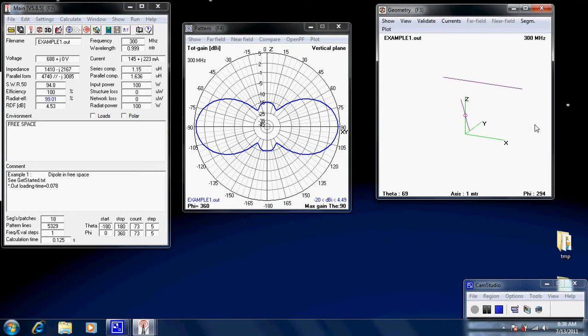The way that you actually enter information into the editors is in 3 dimensions. You have to define an antenna as a point in 3-dimensional space. Now we use the 3-dimensional coordinate system, X in one direction, Y in the other, and Z as the height. So that's all there really is to it. Each wire is defined as a beginning and an end. So each end of the wire will have an X, Y and Z coordinate, and the other end another X, Y and Z coordinate. And that's really all there is to it.